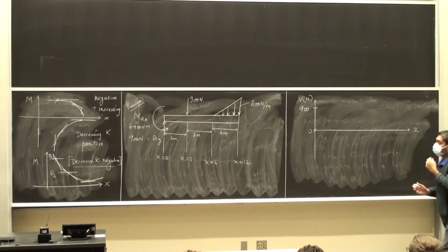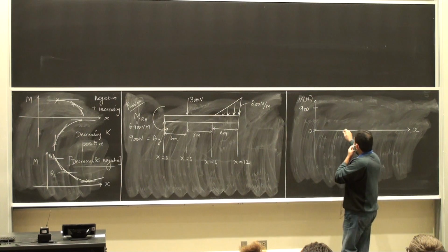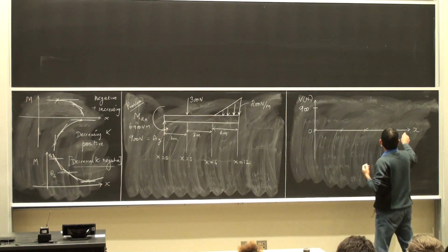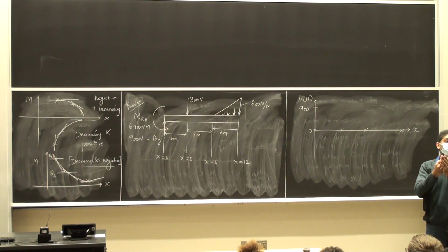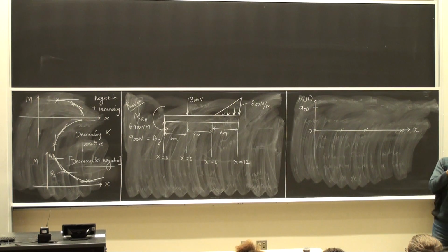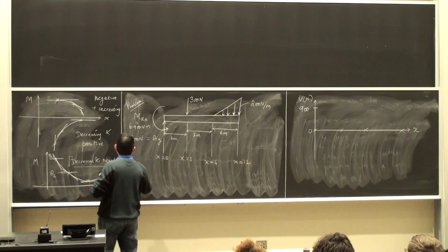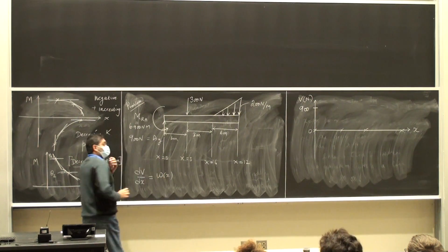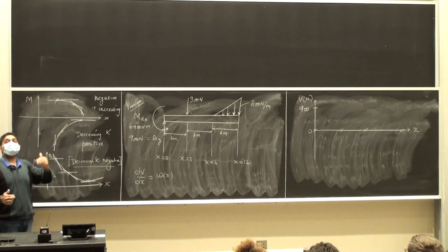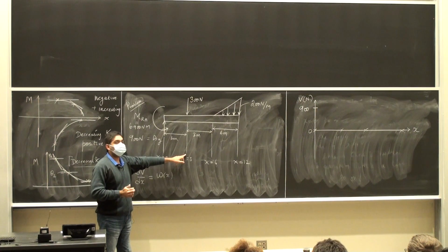My next question, I have to go from 0 to 3. Okay, so here is 3 meters, 6 meters, 12 meters. How do I go from 0 to 3? I have to look at the slope of the shear force diagram. The slope of the shear force diagram, always understand, is equal to the load intensity with the proper orientation of the load intensity between 0 and 3.